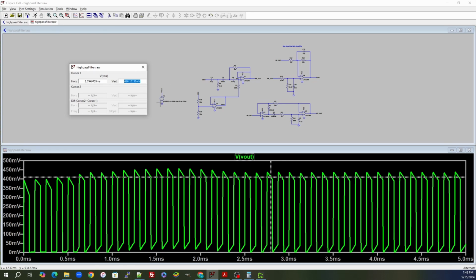and we can go all the way up now to saturation of these particular op amps, because all of them are running off of 3.3 volts, so we just can't saturate any of these op amps and we will be fine. But like I said, it was a small input signal, so a 2-gain amplifier should be fine for a pretty wide swing. So then the question is, well, what do we got to do if we want to adjust this? Let's say we wanted a gain of 4. On this 200 millivolt swing, instead of 400 millivolts, we wanted to see 800 millivolts, so that's a gain of 4.